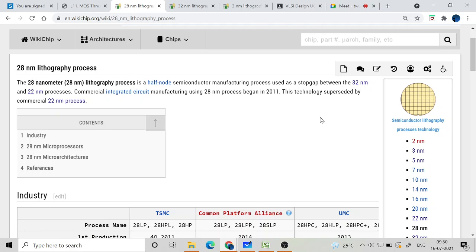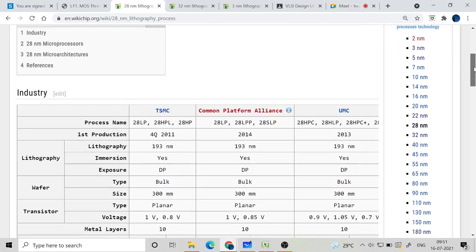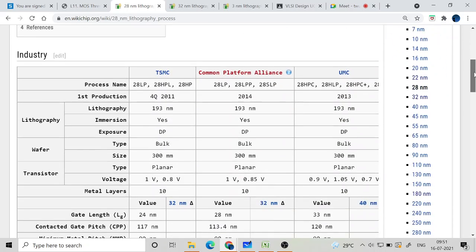So the scaling of MOSFET, when we talk about, say, from 1 micrometer, goes by multiplying by a factor of 0.707. Each 0.707 multiplication takes around 2.5 years, and after many nodes it reached 32, and then it was not possible to go to 22 nanometer. So then what happened? This is the last MOSFET node. 28 was then made.